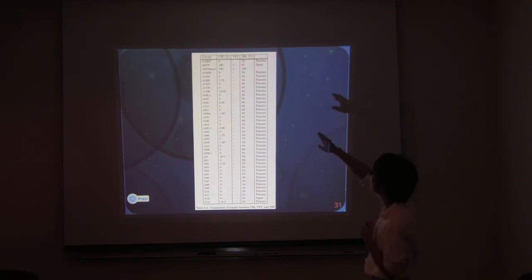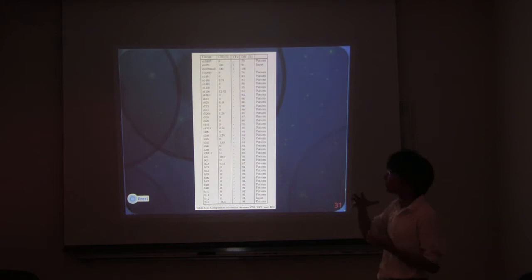However, with DSI, because the modified circuit is smaller, the S5378 circuit would be a supergraph of that circuit, and because it has trouble determining supergraphs, it didn't specify an exact match found. However, compared with the other similarity metrics given, it gave a pretty high rating for that specific circuit, so we can still use that as a way of determining if one is a possible supergraph or not.